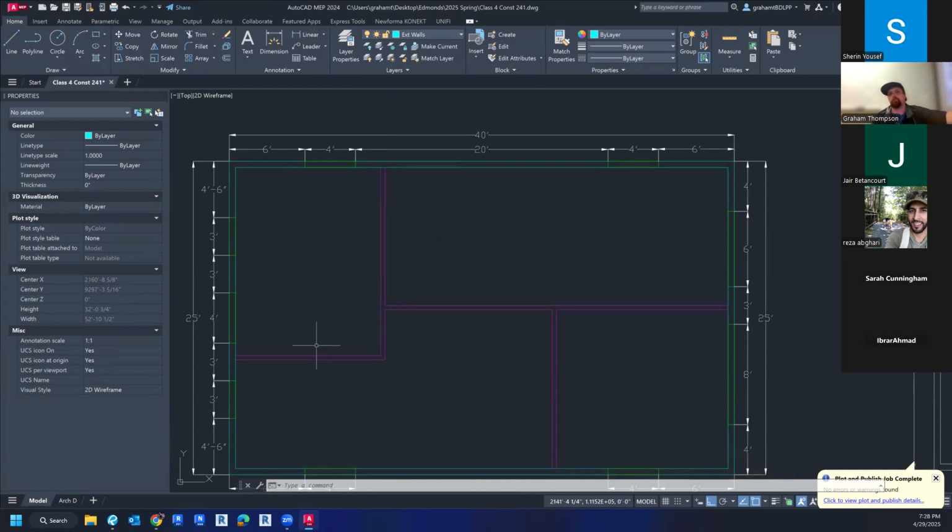Okay. So there's options, right? Use the layers to help you. And they don't always have to be on all the time. Like a lot of times I'll have 30 or 40 layers or work sets. Maybe 5 of them will be on, right? Because I only want to see what I want to see at that particular point in time. I don't care about a lot of the other garbage that you're going to see in background models, right? We're drawing from scratch, which we don't have a lot of extra XREFs or background elements.